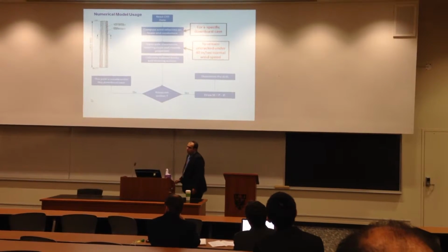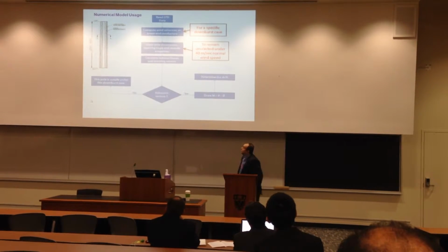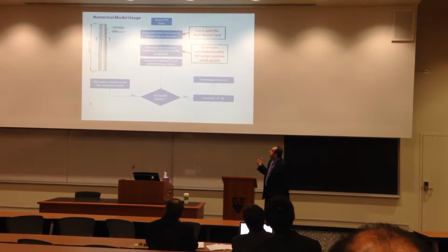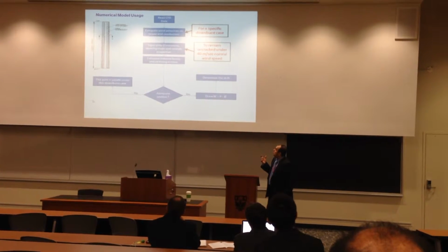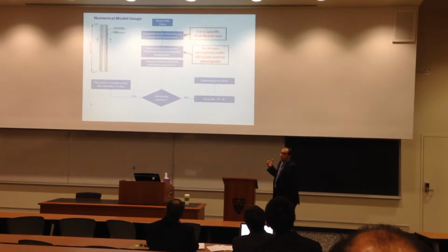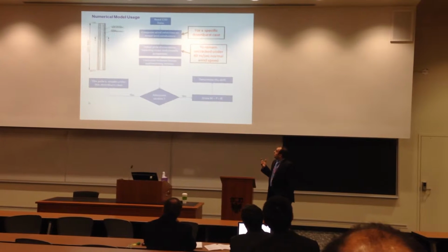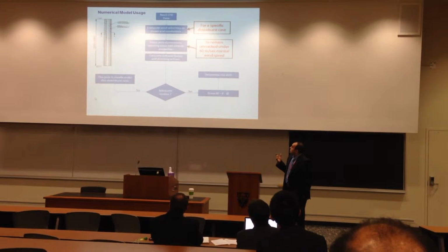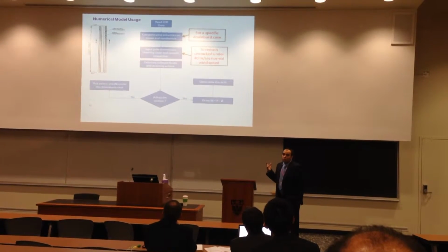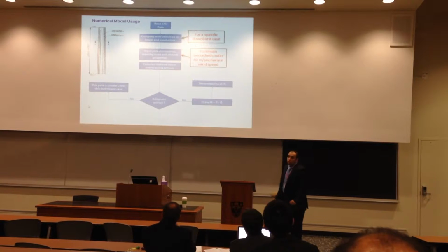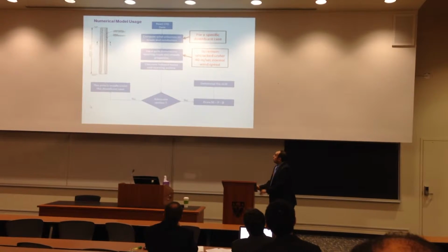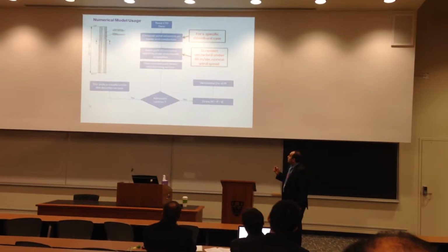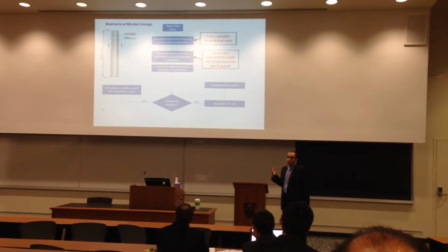The steps of using the numerical model are as follows. We first read the computational fluid dynamics data, and then compute and scale the wind velocity on the tower and conductors for a specific downburst case. Then we input the pole dimensions, tapering slopes, and strength properties such that this pole remains uncracked under a normal wind speed of 40 meters per second. Then we calculate the induced forces and straining actions under this specific downburst case, and check if the section is adequate or not.